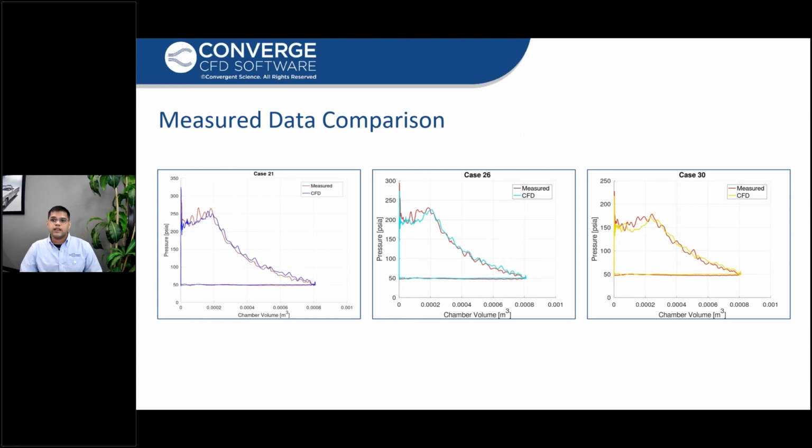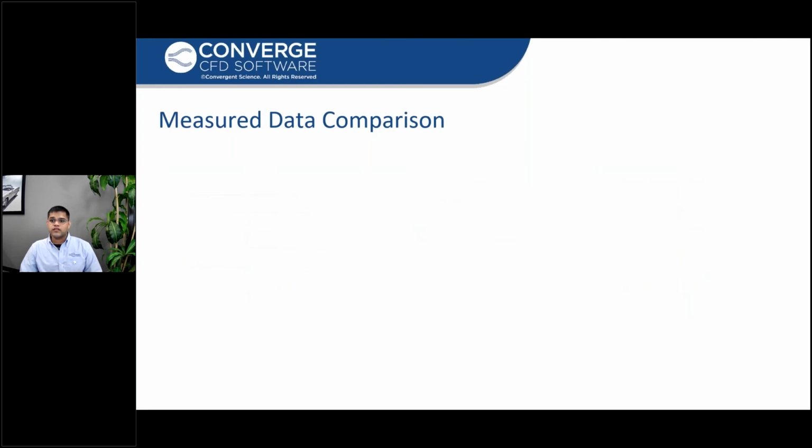What happened is even though we used a fixed outlet boundary condition in the experiments, the boundary condition at the outlet varied significantly, and the discrepancy we observe here is on a similar order of magnitude as the discrepancy that we see in the outlet boundary conditions. Once we look at these indicator diagrams, it's time to compare the global integrated variables.